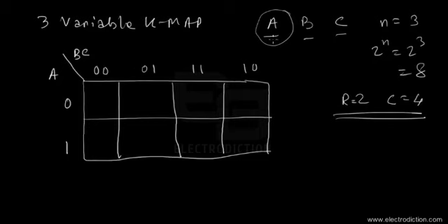Each of the cells over here, if this expression is an SOP expression, will contain certain values. Now we can number the cells over here. So 0, 1. Now again you go back to the last one, and this is 2, and then this one's 3. Okay, and then for the next row you do the same thing. So this will be 4, 5, and then 6, and finally over here you got 7. So this is how you can number the cells for a K-map that contains a greater number of columns, more than 2.